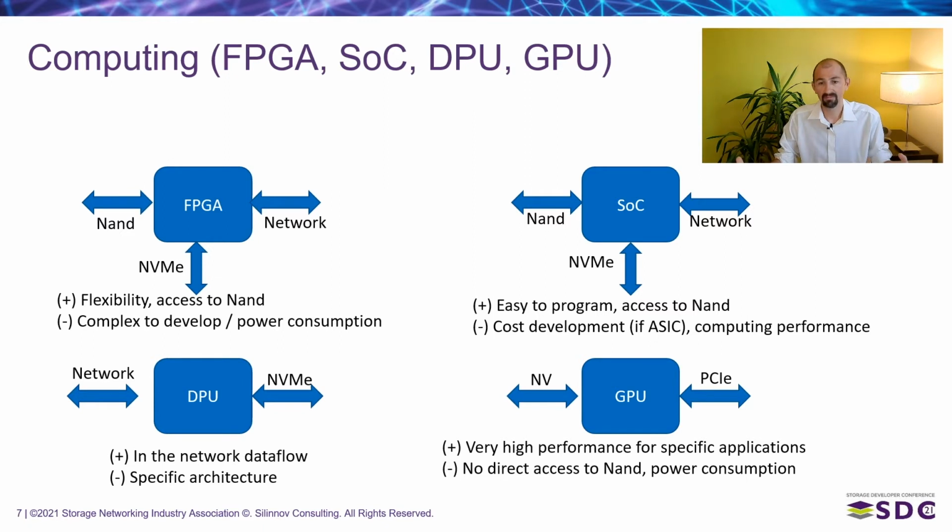First, the FPGA, which is a component well used in computational storage devices for both CSD and CSP. It provides a very good ratio in terms of performance and flexibility. It can address multiple interfaces like the NAND flash, the network, NVMe. On the NAND flash side, with the ONFI interface, for example, you have direct access to the NAND flash component, so very efficient in terms of latency between storage and compute. It can address both application acceleration and storage services for the workload.